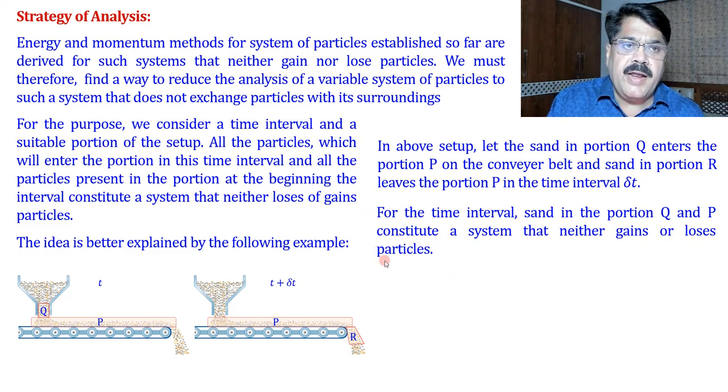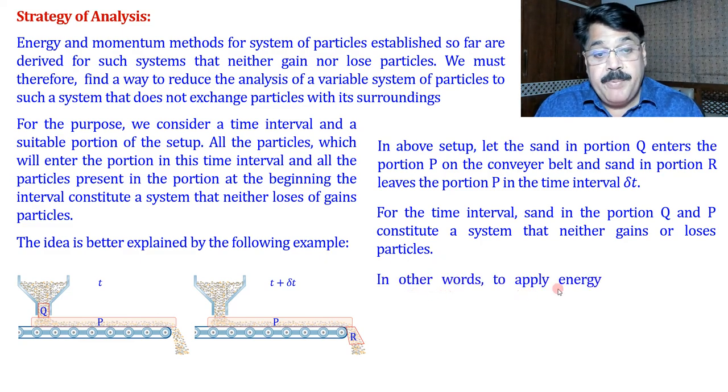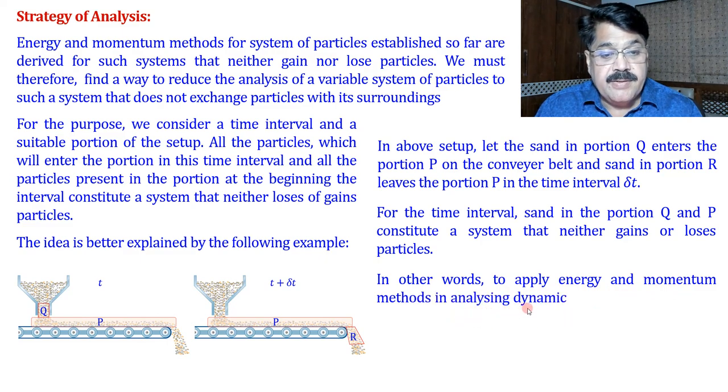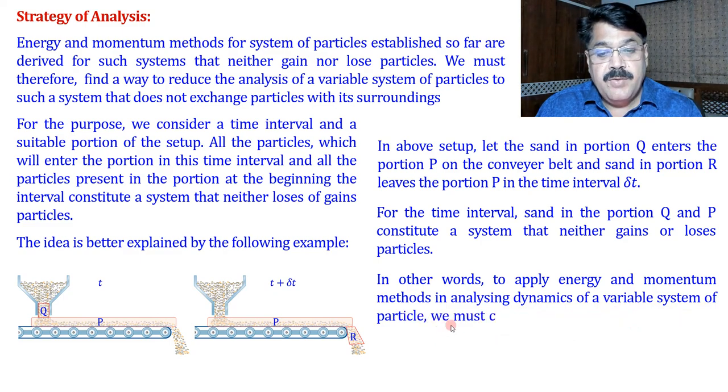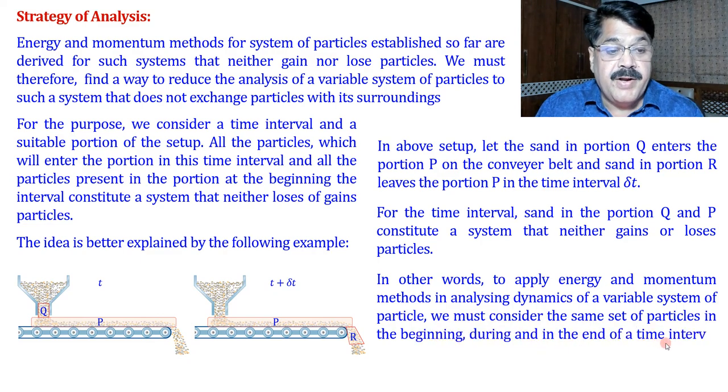The entire idea we can write in some other words also. Let us see here. In other words, to apply energy and momentum methods in analyzing dynamics of a variable system of particles, we must consider the same set of particles in the beginning, during, and in the end of the time interval under consideration.